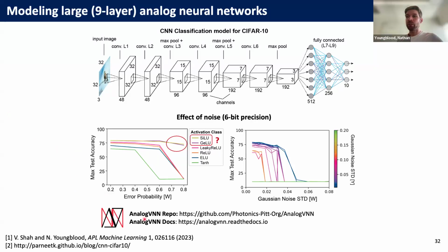Yeah, that's really what motivated us to do this work with analog DNNs, so I would encourage you to look at that. The main conclusion is that for MNIST you can train a network to recognize it even with low precision. But with anything more complicated, like CIFAR-10 or ImageNet, you can actually do quite a bit with 4 to 6 bits of precision in your weights. So the weights matter more than the inputs, and it is possible even with a certain amount of error.